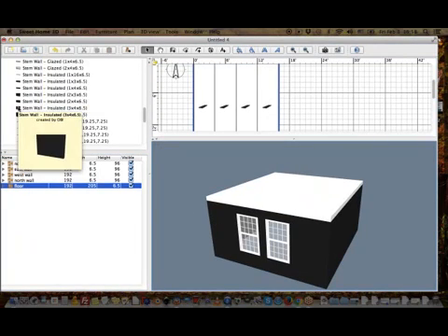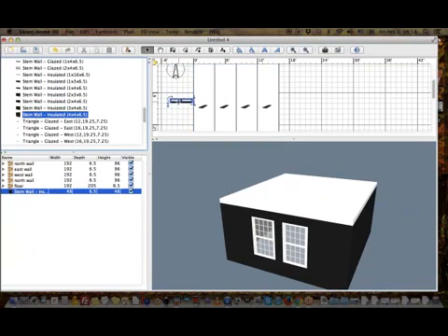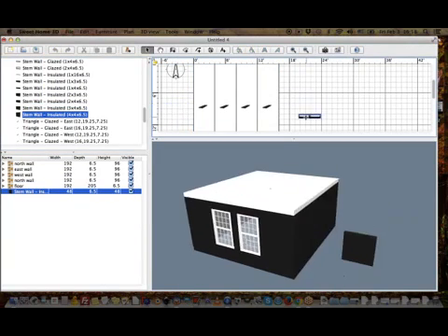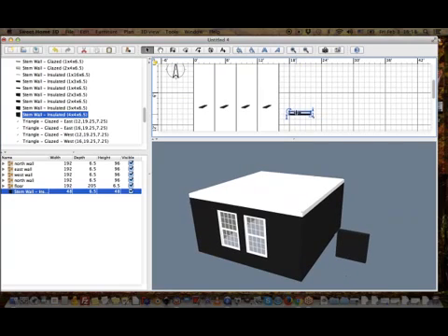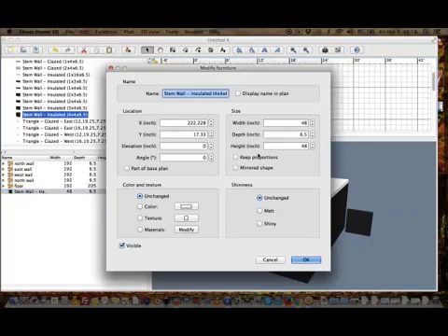Now I'm just going to do really quickly a second story. So I'm going to drag on this other module that is just like a little wall. It's a short wall. And I want it to be, once again, on the 0 point. So 24, 3.5. And I want the elevation of this one to be the height of the wall plus the thickness of my floor.